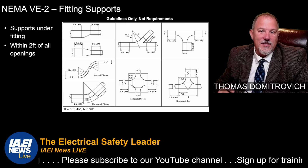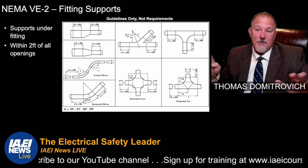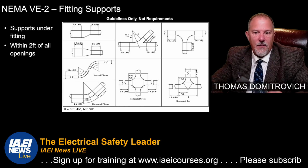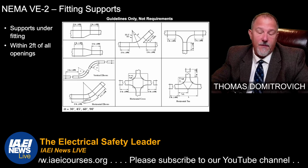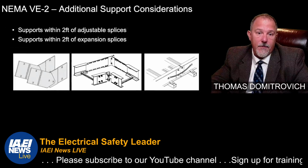Fitting supports. These systems can get pretty cool. Within 2 feet of all openings, support under the fittings, and they'll give you this great information. You can pull these from manufacturers. Manufacturers will give you the information that you need to install their cable tray.